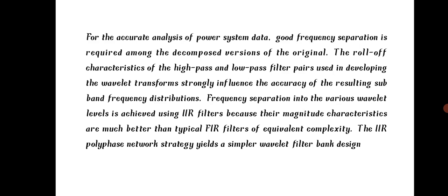Frequency separation into the various wavelet levels is achieved using IIR filters because their magnitude characteristics are much better than typical FIR filters of equivalent complexity. The IIR polyphase network strategy yields a simpler wavelet filter bank design.